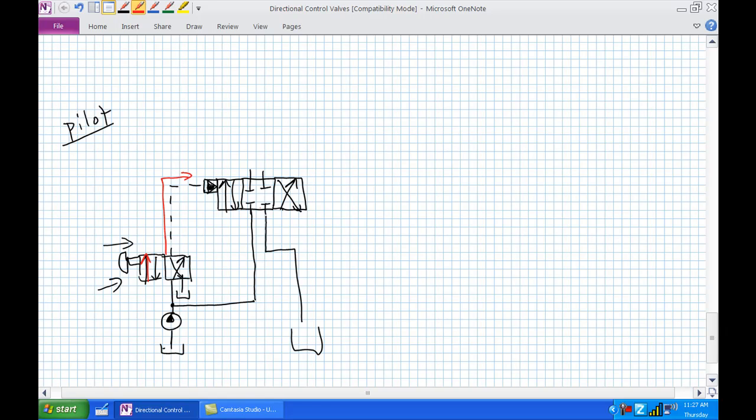Sometimes what you might see is, well, what's the advantage here? Basically, it's all the same system. You're already using hydraulics, so you can just use pressurized fluid flow to hold the pilot activated valve in a particular situation. The other thing that's going on here is, pressurized fluid flow inside the pilot doesn't need to be a lot of fluid flow, nor does it have to be at incredibly high pressure. But let's say you are working with an incredibly high pressure application.